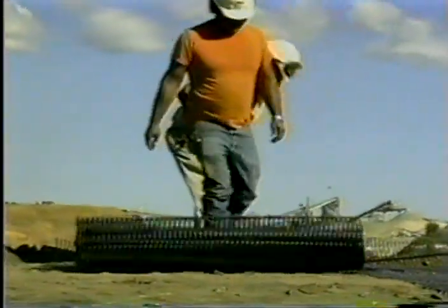This type of geogrid is formed by punching holes in an extruded HDPE sheet and drawing it out in one direction to form a uniaxially strengthened grid. This one is made by punching a polypropylene sheet and drawing it in two perpendicular directions to form a biaxially strengthened grid with near-square apertures. Other geogrids are made from woven or knitted polyester straps.